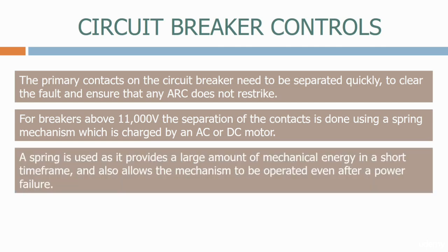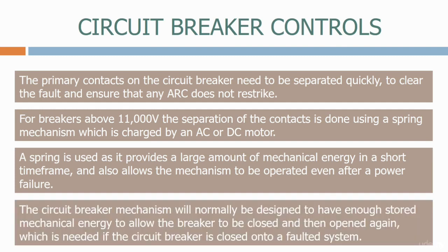A spring is used as it provides a large amount of mechanical energy in a short time frame and also allows the mechanism to be operated even after a power failure. The circuit breaker mechanism will normally be designed to have enough stored mechanical energy to allow the breaker to be closed and then opened again, which is needed if the circuit breaker is closed onto a faulted system.